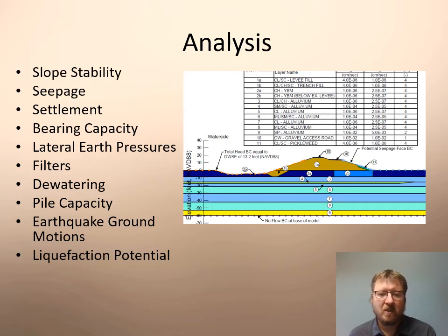So during construction, it's important to keep the construction area dry, and the dewatering is important. If you're building structures, pile capacity, both axial and lateral, is important. In some situations, in high seismic environments and kind of a permanent pool condition, the geotechnical engineers are asked to produce earthquake ground motions and probably assess liquefaction potential based on the conditions of the site. So there's a lot of different things that the geotechnical engineer does with all that information.